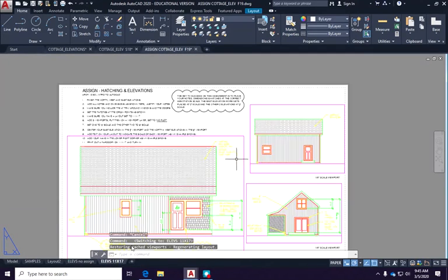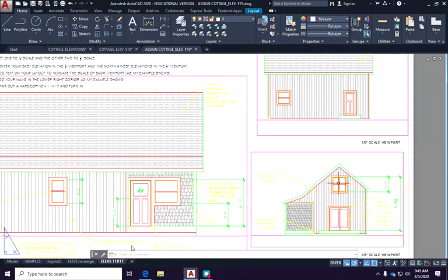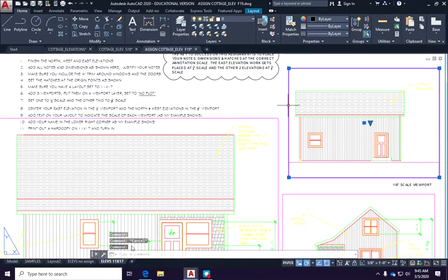There we go. So when we put them in the layout, you'll see that these two guys are 1/8 inch. That roof shake siding is small over here, but twice as big over here, even though I put it in at the same scale. My vertical siding shows close up, large over here, skinnier lines over here because that's a 1/4 inch and these guys are 1/8 inch. But if you look at these two, the ANSI hatches, the line pattern is exactly the same scale, even though that's a 1/4 inch and that is a 1/2 inch.